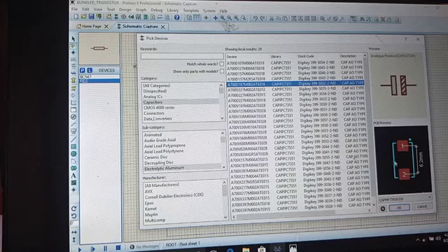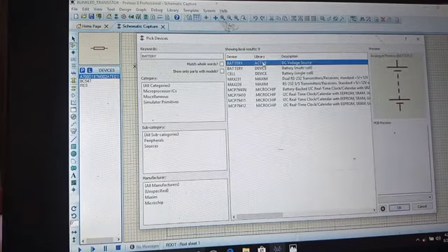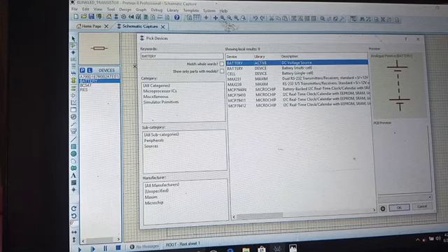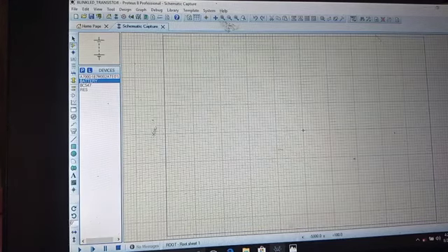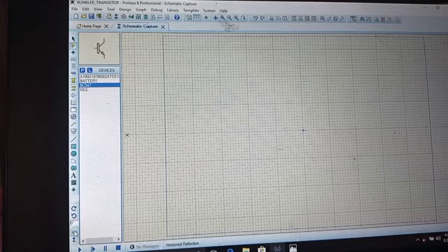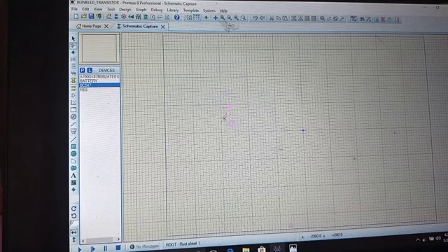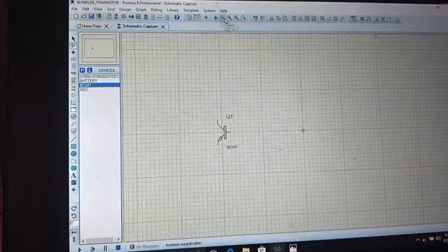For capacitor, it may be difficult to just search a capacitor directly, because when you press cap, you're likely to see ceramics. So you have to select capacitor. Then under the categories, when you look directly under that menu, you select the type of capacitor that you need. After picking our components, we now have to drop them, starting with the main IC, which may be the transistor.